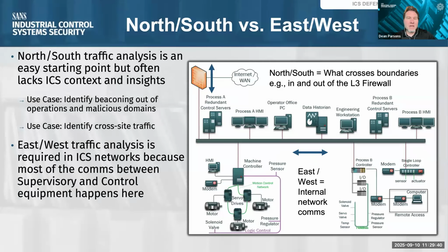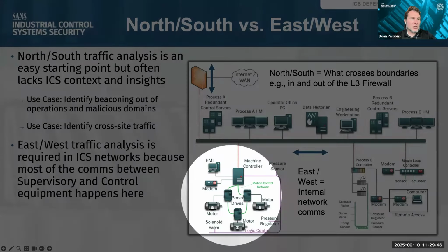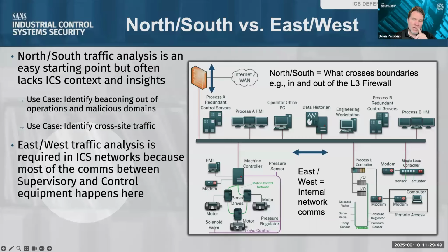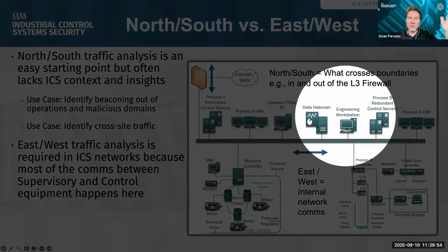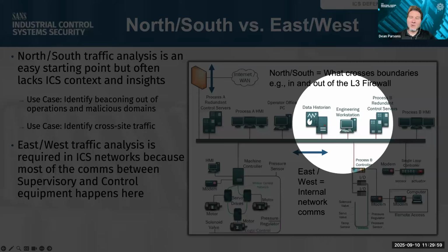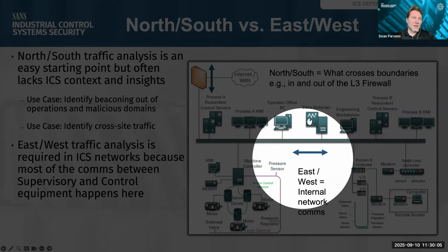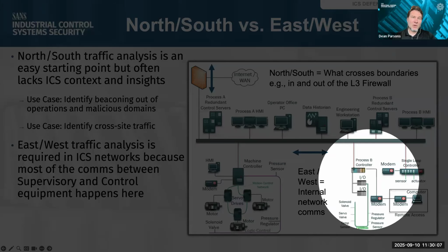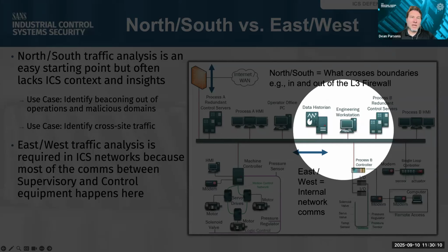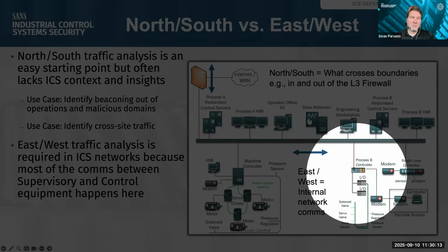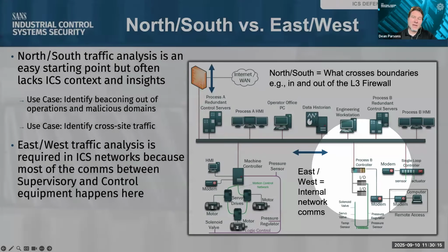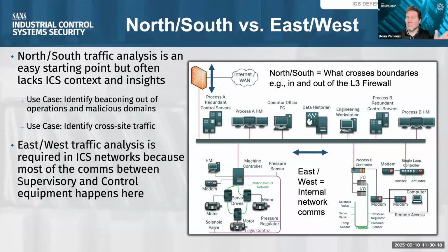Here's an example. Because we can now get information inside the ICS, specifically, we're looking at communications now of the control system protocols. We can now detect things even like living off the land. An adversary possibly is here, like we've seen with Trisis and so many other types of attacks in ICS. Here at this level, the engineering workstation is used to program the PLC. And down lower in the control system environment, where the PLCs are, that device will communicate through the network using an ICS protocol to a controller. That is now captured using east-west visibility and monitoring.